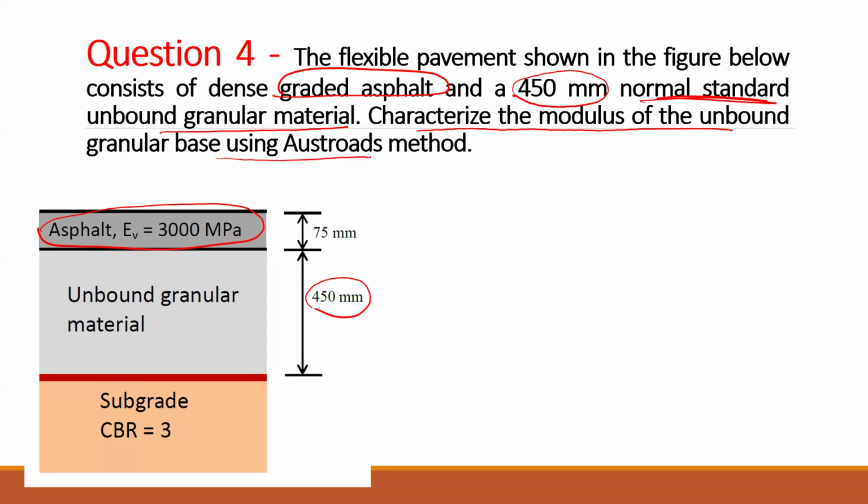So finding the modulus is very important. When you do the CIRCLY experiment, we have to give those values, modulus of different materials. So here, modulus of the subgrade, if you know the CBR, have you done soil before? So you know the bearing capacity of soil, isn't it?